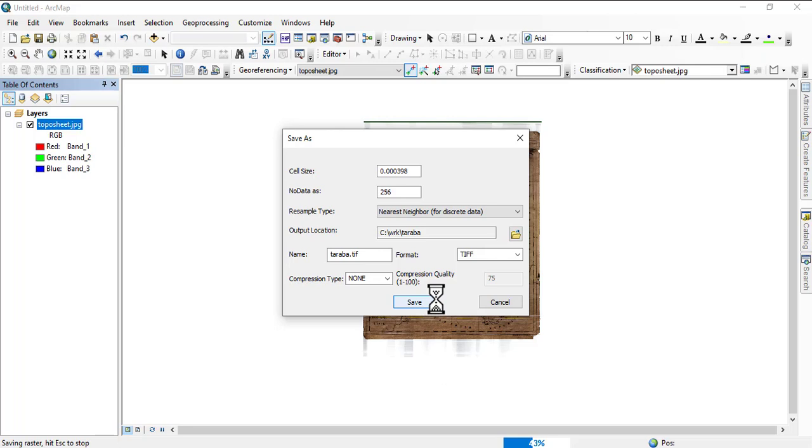So once that is rectified, you basically have come to the end of your georeferencing. But we are going to also use this method, and then we're going to check our residual error to be sure and see whether the residual error between the one of today and that of yesterday are the same, or this is an improved resolution or improved accuracy than that of yesterday. We're going to check on that once this is done.